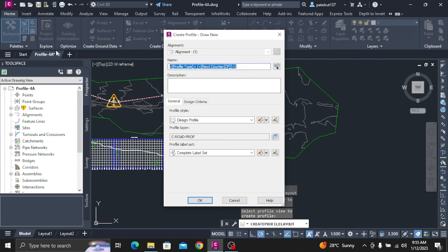Right-click. Click Profile View Properties. In the Profile View Properties dialog box, on the Projections tab, clear the 3D Polylines checkbox. Click Apply. The 3D polylines are removed from the profile view and are cleared from the Profile View Properties dialog box. Click OK. Open Profile 5D.dwg, which is located in the Tutorials Drawings folder.